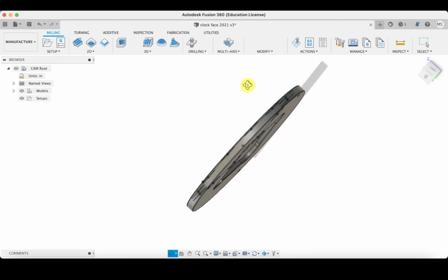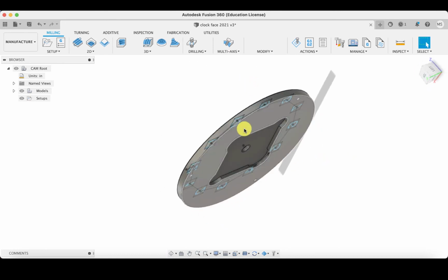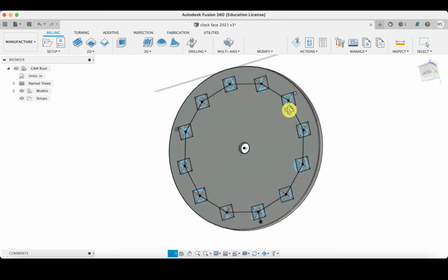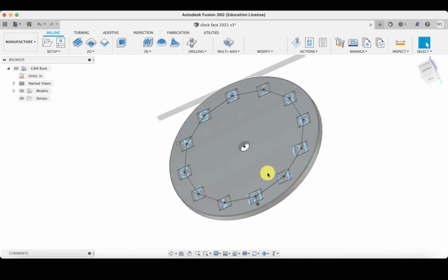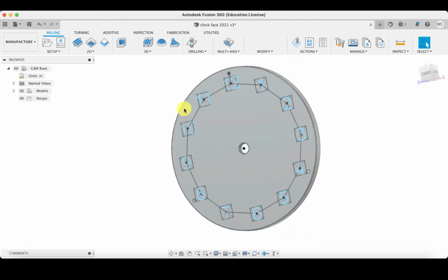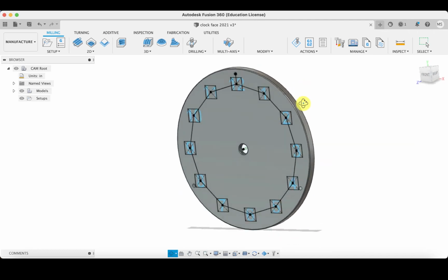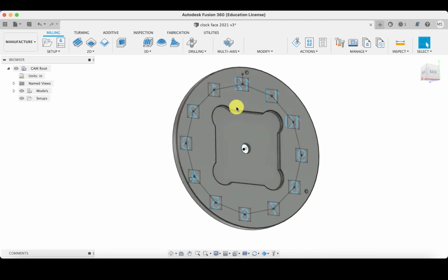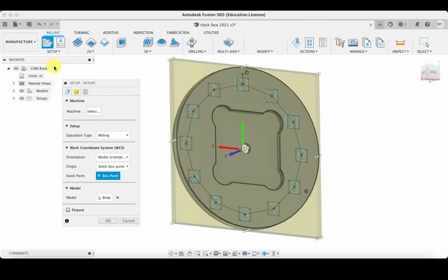provides a pocket that goes over a fixture, and then a bolt goes through the hole, holding the material tightly to the fixture so that the front can be milled. So we have two different processes, milling the back and then milling the front. So we have two different setups. So the first setup I'm going to call setup 1, and that's milling the back. So I'm going to go to setup and click new setup.